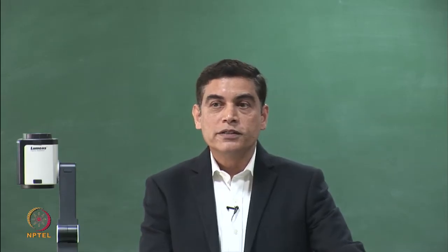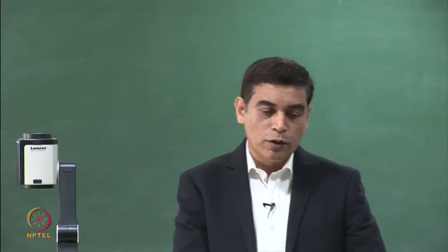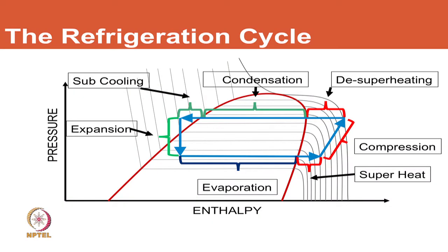However, if we wanted to go to higher efficiencies, we would do two things. We would lower the condensing temperature. So the compressor work is dependent on these two parameters. One is the saturated suction temperature or the evaporating temperature, and there is a pressure corresponding to that on this chart. So these two points are clearly determining the work done by the compressor. So if we want to target a higher efficiency, we would attempt to lower this. Is that clear? Is it making sense?